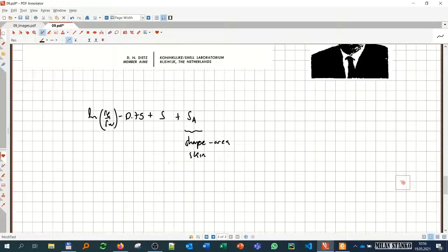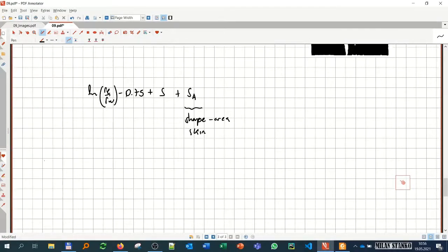If we have any area, seen from the top where we have a wellbore, we can always put it in terms of some equivalent external radius. So we can say this is pi RE squared, and we end up with RE equal to the square root of A divided by pi. And we can include that radius into this lower part of the productivity index.